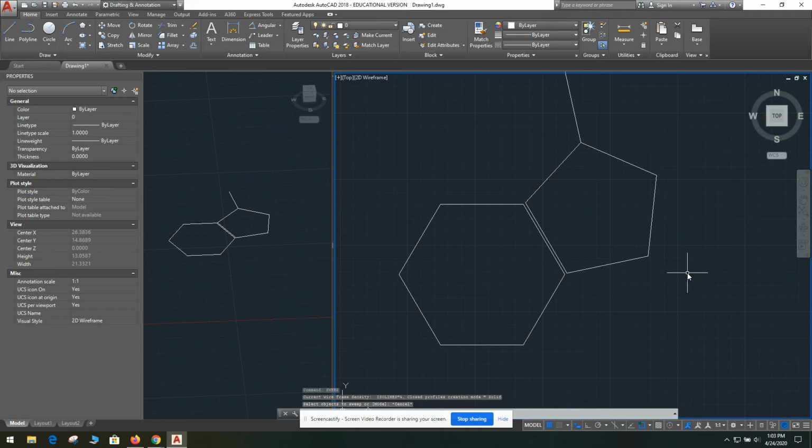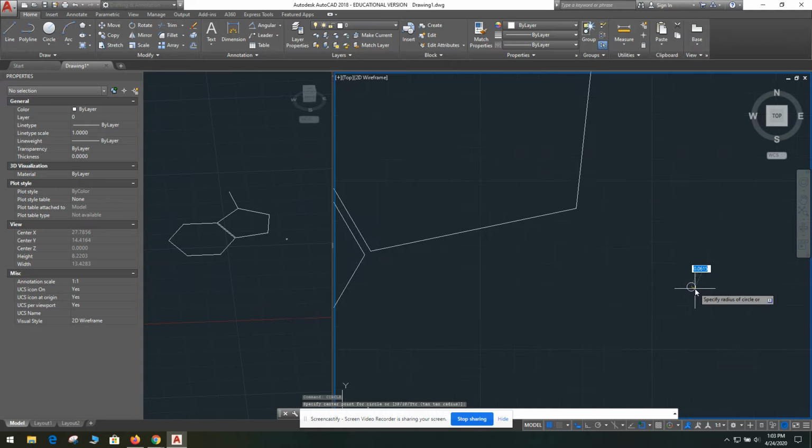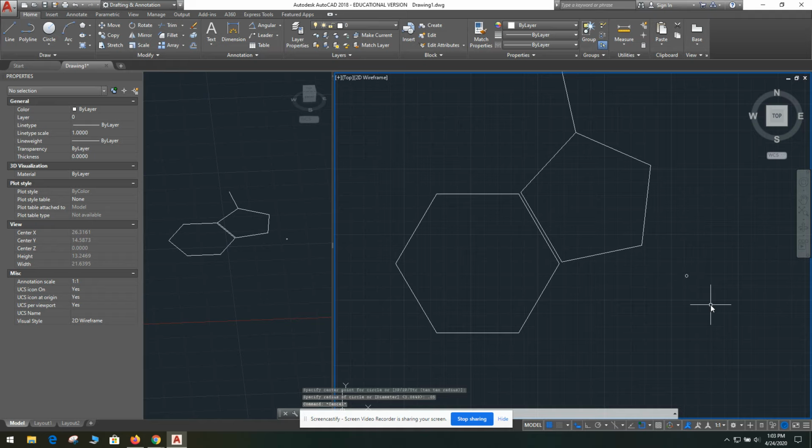And remember that it's a circle, because you're making a bond, and it really doesn't need to be much. If it's too large, it's not going to give you the space for the double bond. So I'm just going to make it 0.05. It's teeny, and that's totally fine. But remember, once you make the sweep, you no longer have these angle points.